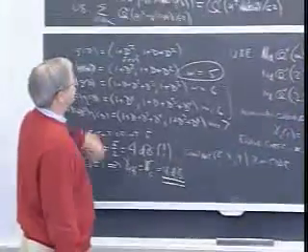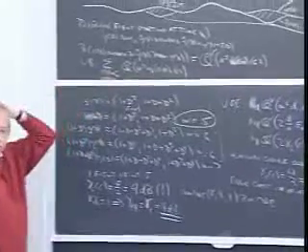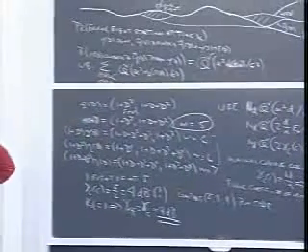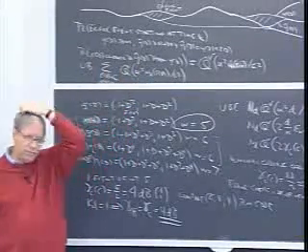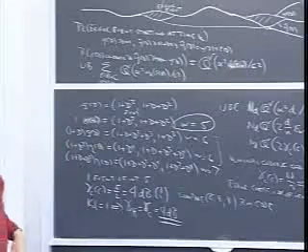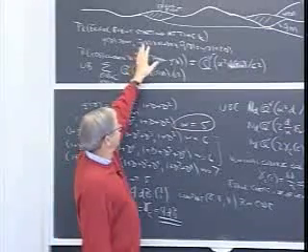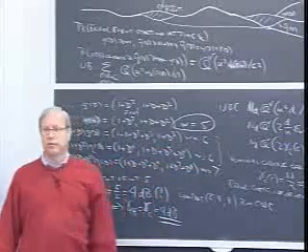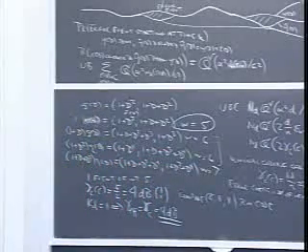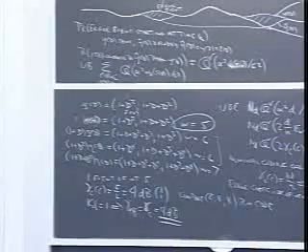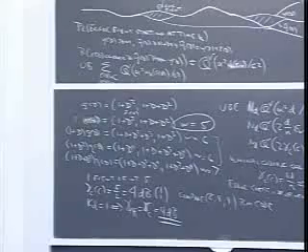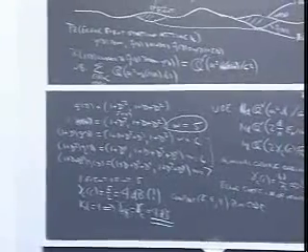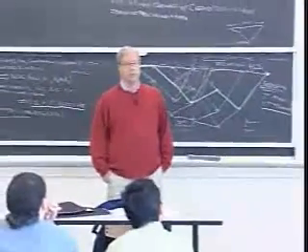You see, you're going to get bursts of errors in your decoded sequence. It's a very natural idea to have an outer code which is based on GF of 256, say, 8-bit bytes. And so a Reed-Solomon code comes along and cleans up the errors that do occur and drives the error probability down to 10 to the minus 12th, or whatever you like, with very little redundancy, very little additional cost. So that became the standard approach for space communications in the 70s and indeed 80s.